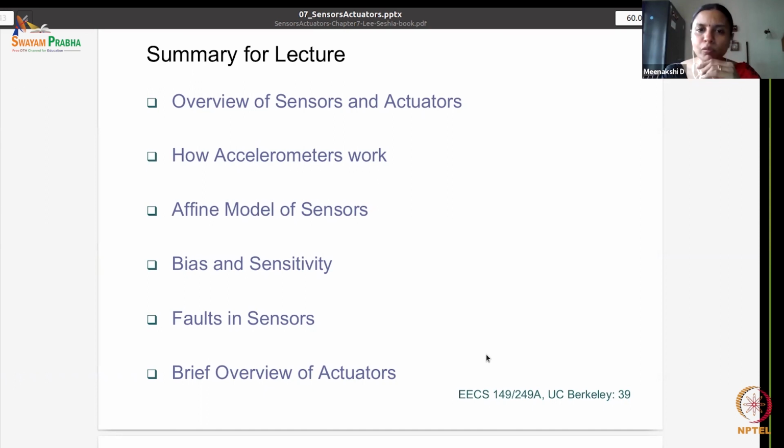What are the types of memory? Is it volatile or non-volatile? Volatile versus non-volatile means: am I going to remember things when there is no power, or am I going to remember things only as long as there is power? Is it SRAM or is it DRAM? What is going to be my memory map? Is it going to be based on a certain kind of architecture? Is it going to be based on input output? How is my memory going to be organized?